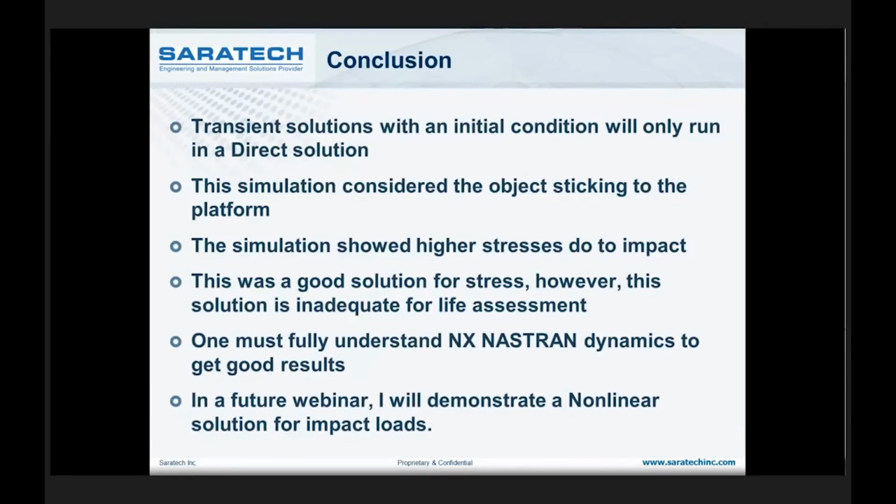One other thing is this is a dynamic simulation. One must fully understand NX dynamics, or dynamics in general, to get good results, because Femap allows you to set up an easy dynamic solution. But if you don't know what you're doing, you can easily produce bad results.